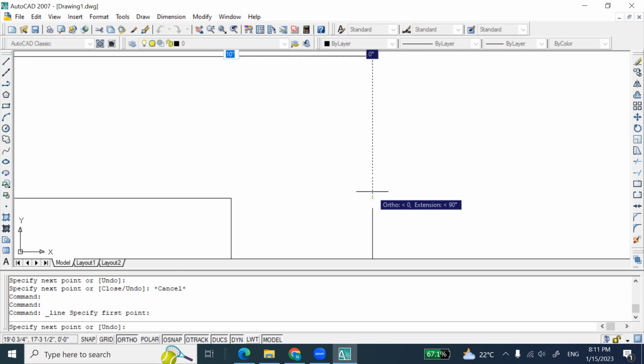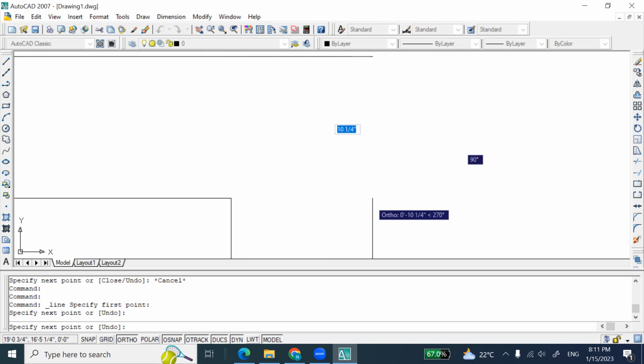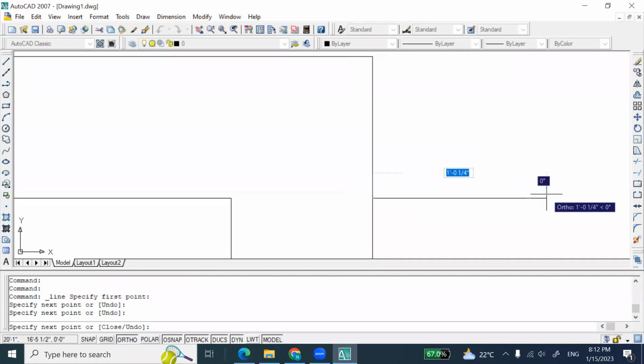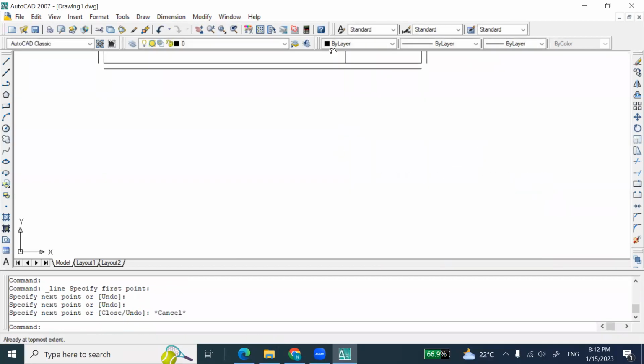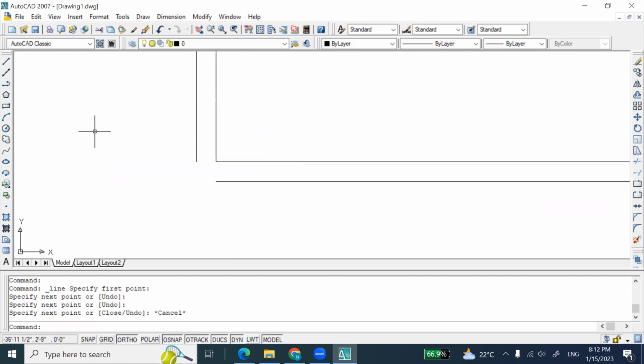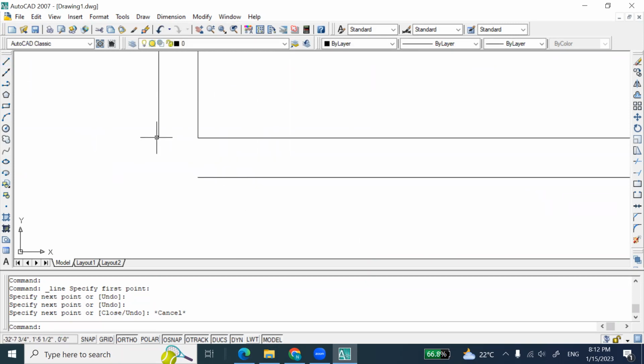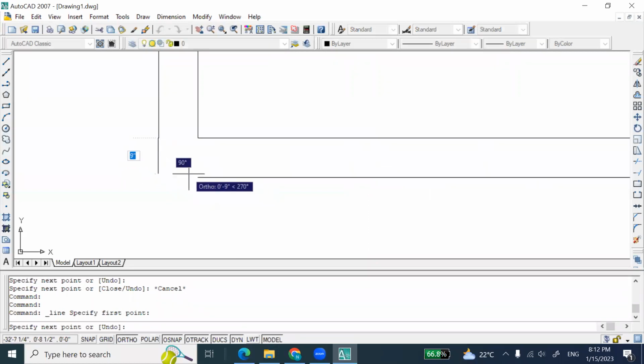When you can see the dotted line, left click on your cursor, and again when you can see the yellow square, left click on your cursor. That's it. It's still a little bit tough, but I think once you get it, you can understand.